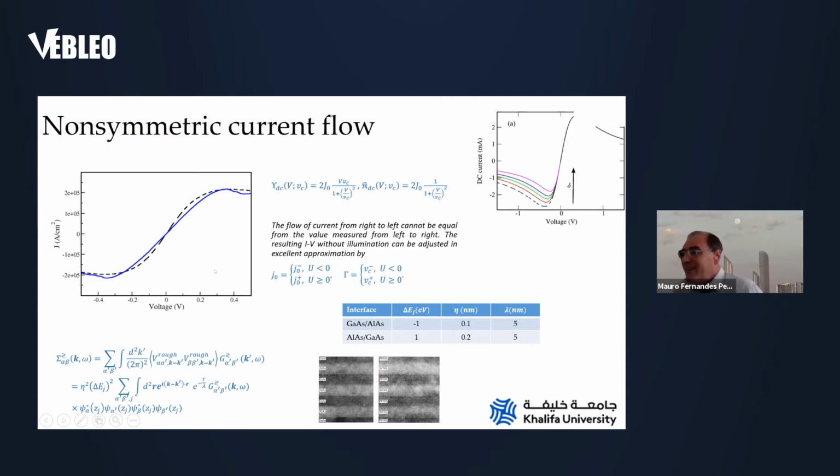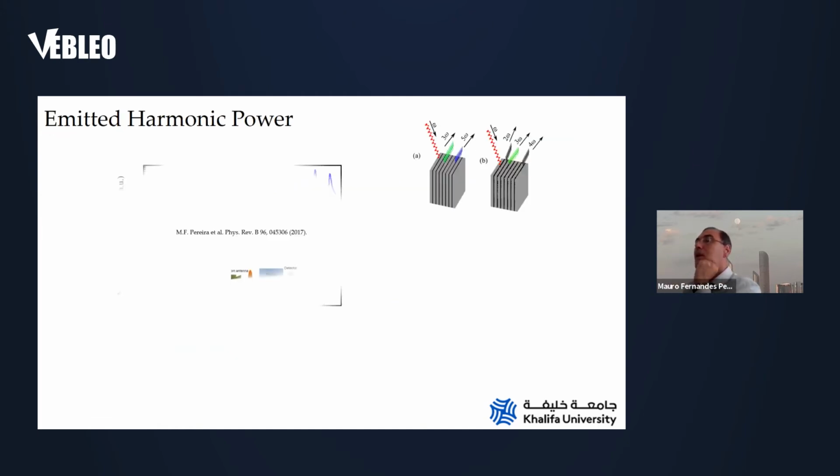And I don't really have an exact solution for the case of asymmetric current voltage when this peak is not equal to this. So I use an ansatz, in which I assume that the peak current here is different from here, and the turning voltage here is different from there. So this ansatz solution allows me to modify the analytical solution and get working relations for the power output based on this nonlinear current that we see here.